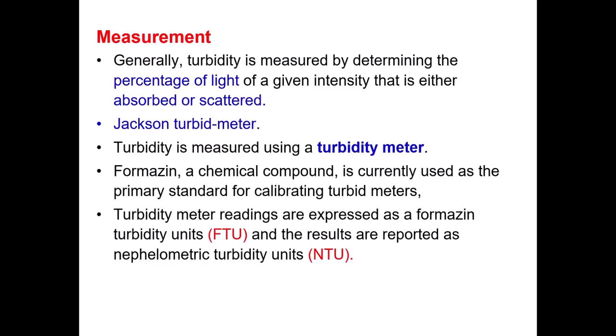Calibration now uses formazine, an organic compound. 1 milligram per liter of formazine is 1 FTU, 2 milligrams per liter is 2 FTU. Some devices use NTU instead. NTU stands for nephelometric turbidity unit. Jackson devices are rarely used today, mostly in museums only.